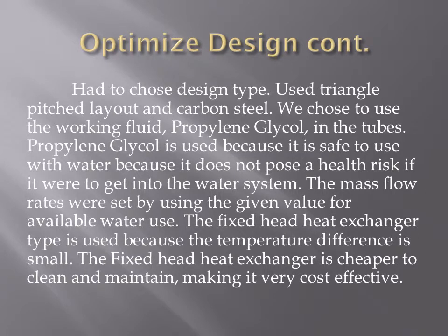To optimize the system, we had to set some of the values as constant. We set the pitch layout as triangle pitch layout. The material we used is carbon steel, and we chose propylene glycol as our working fluid because it is safe to use with water if there is any sort of leak. And we used a fixed head system for our heat exchanger.